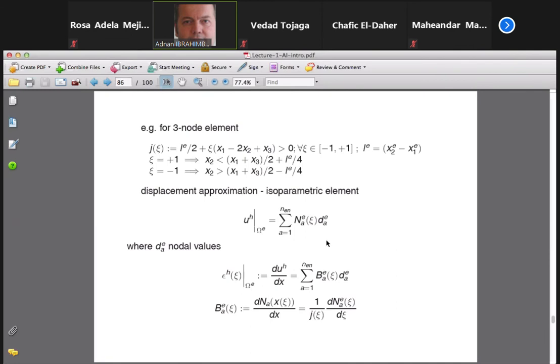So this is the kind of approximation that one has to respect, and it is the first case of what happens when the element is distorted. In other words, the higher the element order, the more precise you are, but only under certain ideal conditions. You do not necessarily have these wonderful conditions all the time. So basically, you have to really worry about how you actually construct this for the higher order elements, and you worry about element distortion and so on and so forth. So once you have your displacement interpolations,